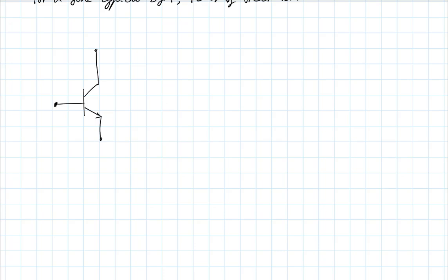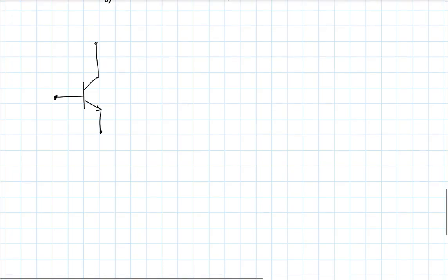And then you had some gate in the middle that could deflect the electrons one way or the other and prevent them, for instance, from reaching the collector, or modulate the number of the electrons that reach the collector per unit time. So there are a lot of similarities. And in fact, if you want to understand these devices well, I personally think you should start with vacuum devices. And we'll see if we have time to discuss that later on. But the names emitter and collector and base are very meaningful.